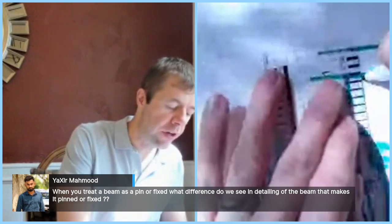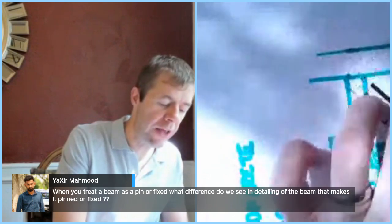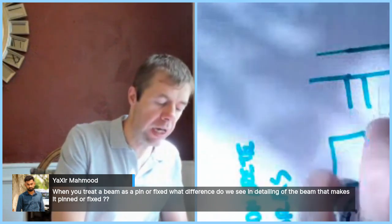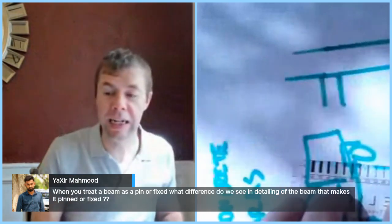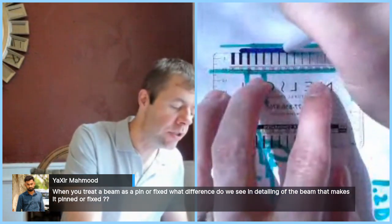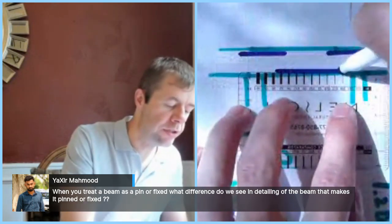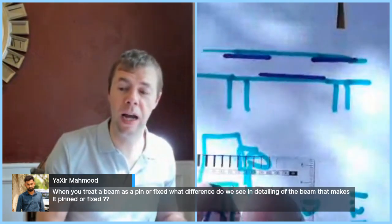So if I have a column and I want to treat it as a fixed beam, then I need to design it to be a fixed beam. As in, I need to design tension steel up here, tension steel down here, tension steel down here. I need to just design for that.